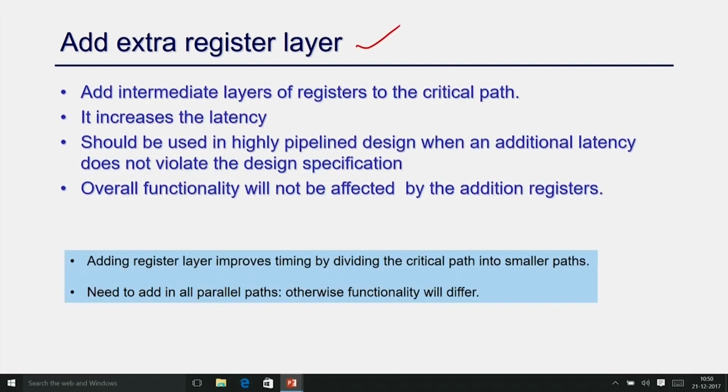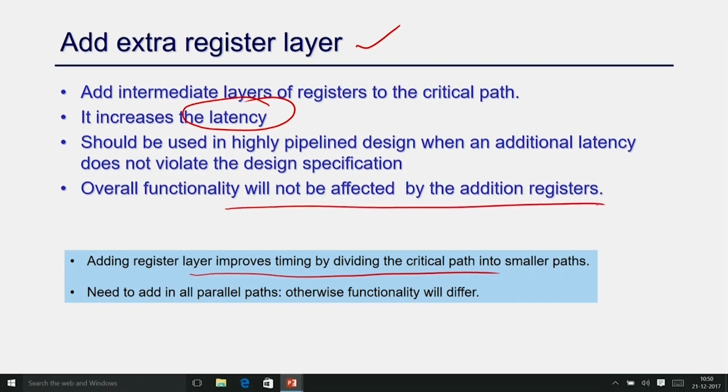So, what I just said is that adding a register layer improves the timing by dividing the critical path into smaller paths. But it increases the latency, right. Obviously it is going to increase because you are adding a register to your design, but you have to be careful about this.